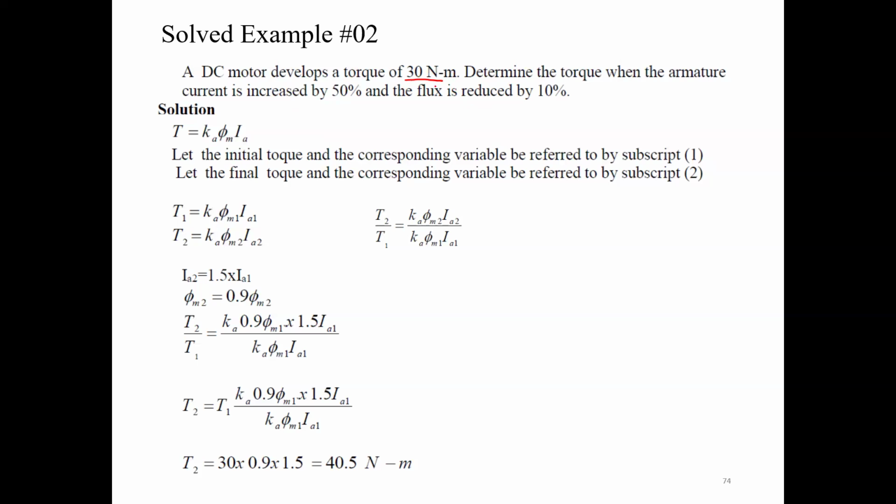So this is a matter of comparison here, guys. And the interesting thing in a DC motor is the linear relation between torque and current. So we can relate the values. So we can say that torque is proportional to IF times IA. Because you know the exact relation is torque equals constant times flux times IA, or constant, let's say this is with prime, times IF times IA.